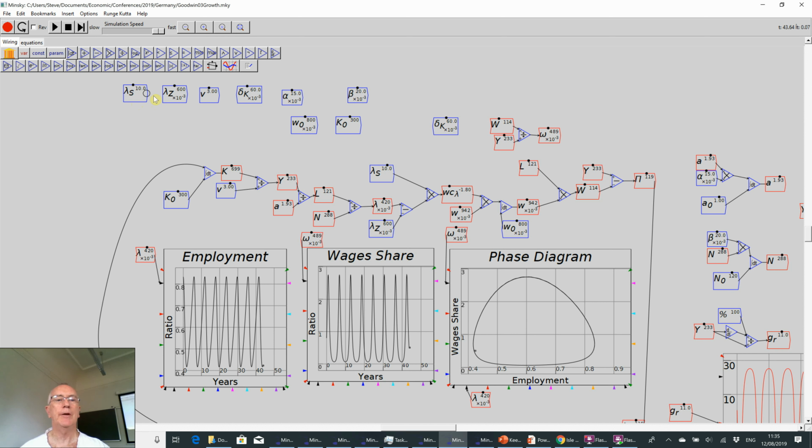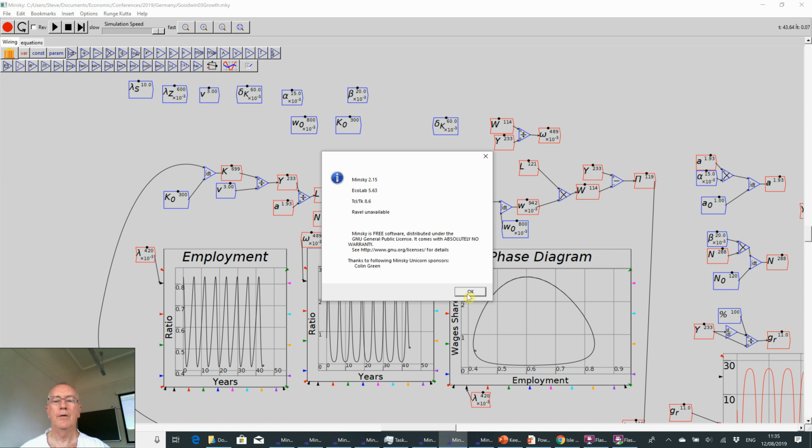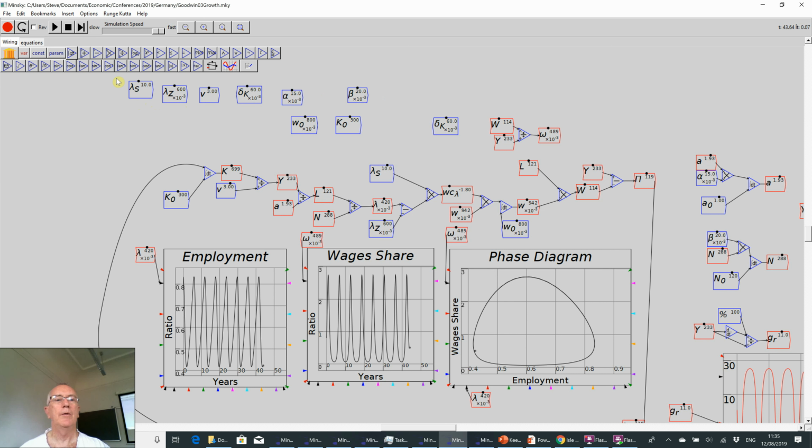In the beta, if I want to select things, I hold down the control key. Okay, what's wrong? This is not the beta. Having selected them, put them in the same area, I'm going to group them. So I right click and left click and drag a rubber band around them, and then I choose group.